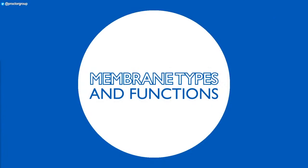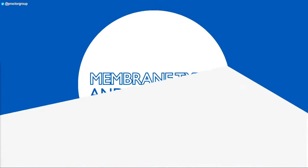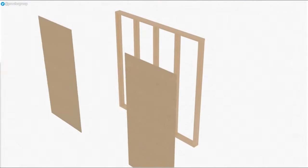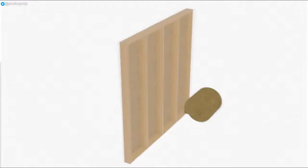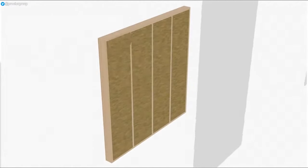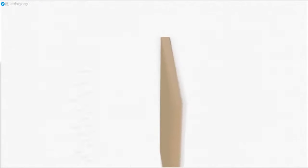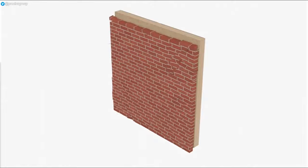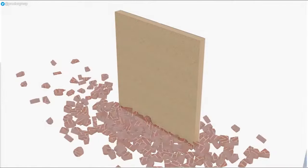To illustrate the way we can use construction membranes to counteract the harmful effects of moisture, we'll consider a typical domestic timber frame wall built using an open panel construction. This type of wall usually consists of structural timber stud-work with a sheathing board of OSB or plywood supplying racking strength. The principles of membrane use apply similarly to all the construction types we've discussed, however.